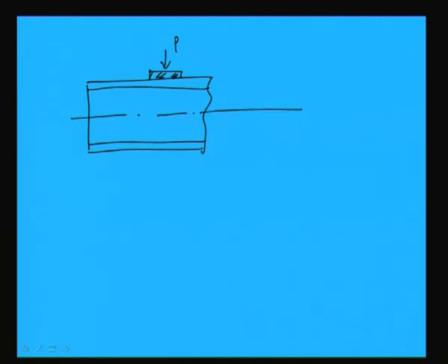So, this is the plate. Now, if a concentrated load P is acting here, as per the assumptions it will be dispersed at a 45 degree angle, right.